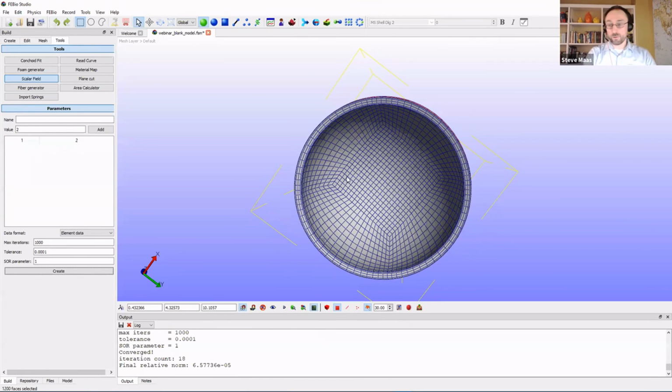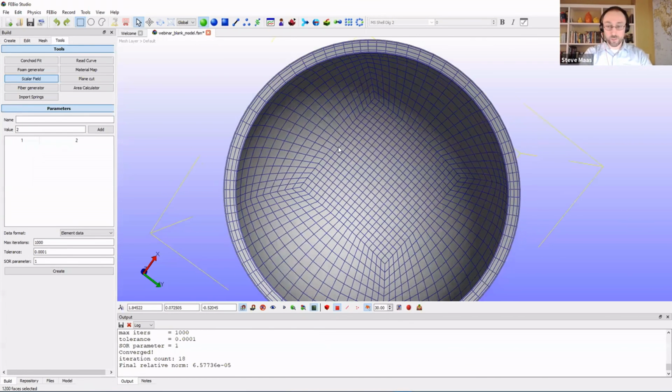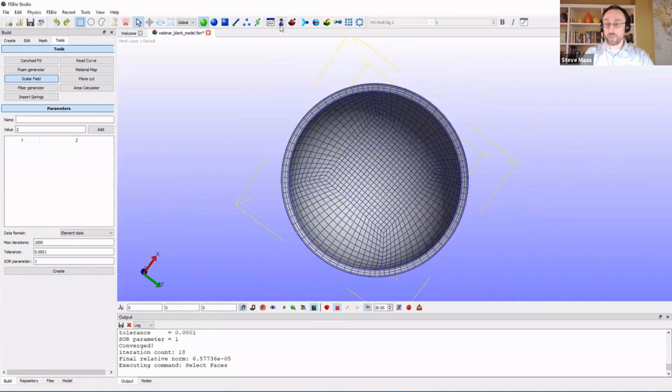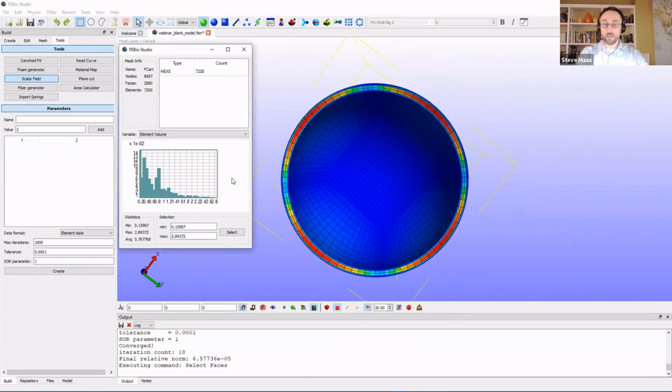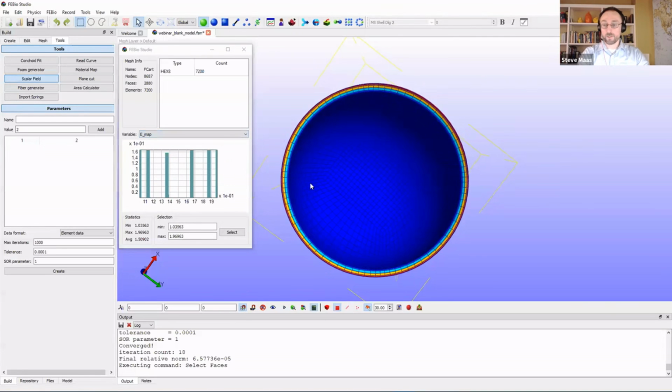So how can we see the result? Well, to see the result, we go to the mesh inspector here. The mesh inspector allows you to look at various measures over the mesh. So you can look at volume, Jacobian, some quality measures, and we'll come back to these in a minute. We're looking at some tetrahedral meshes, and at the bottom is the map that we created.